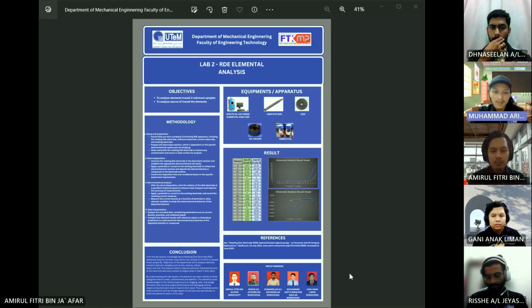of wear debris. Calcium levels display a significant difference between the two samples. The new oil sample B has a concentration of 58.24 ppm, whereas the used oil sample B1 displays a substantially higher concentration of 313.14 ppm. The increased calcium content in the used oil suggests the presence of calcium-based additives or the ingress of external